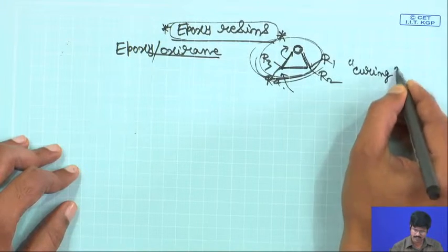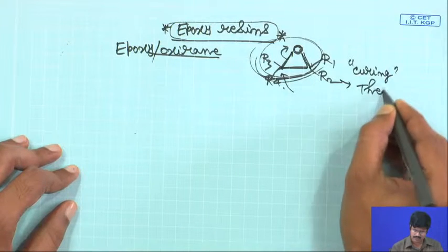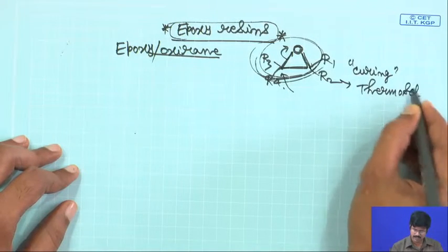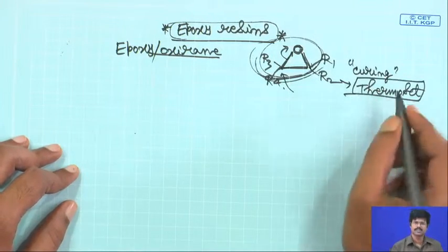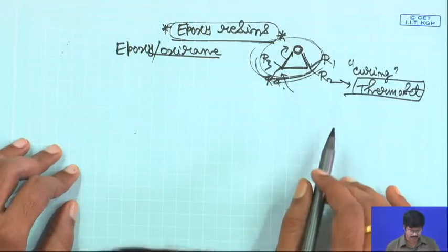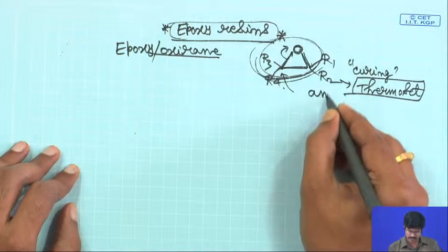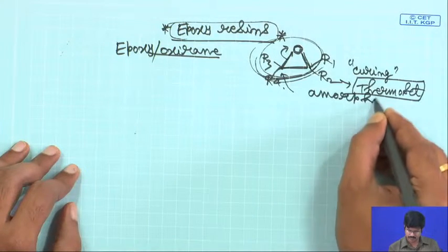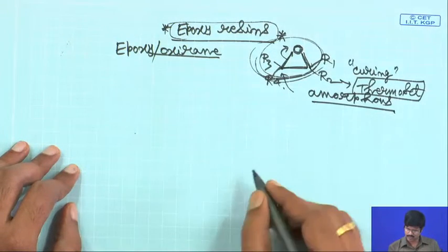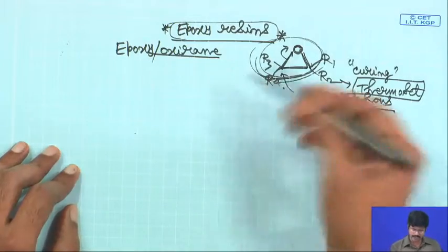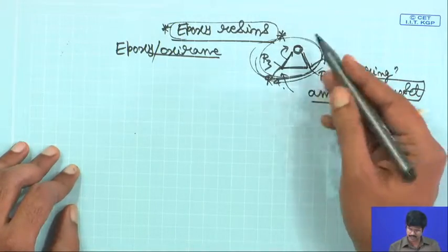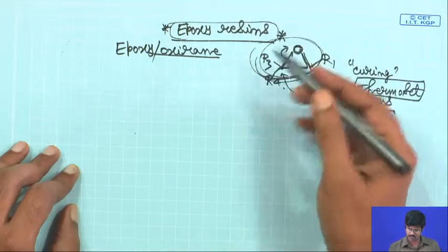Ultimately what you can get are thermoset materials, which have permanent cross links which cannot be further processed by heating, and typically these are amorphous thermoset materials, and they will have excellent mechanical strength and toughness, good adhesive properties, so on and so forth,